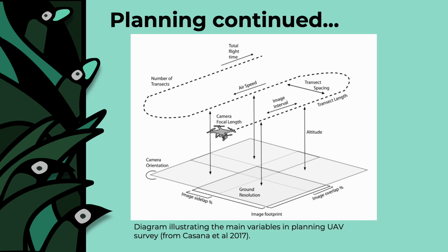Electrically powered UAVs usually offer between 20 and 30 minutes of flight time per battery, while newer, more expensive models can offer close to 1 hour of flight time. Since battery life varies with air temperature, wind velocity, and battery age, it is practical to limit flights to no more than 80% of estimated battery duration. The efficiency of semi-autonomous flight planning software can enable flights over smaller areas using only one battery.